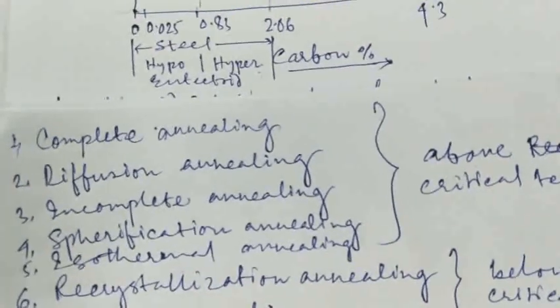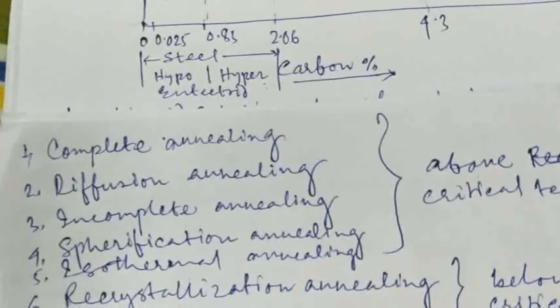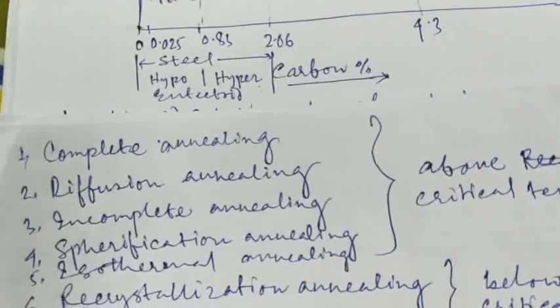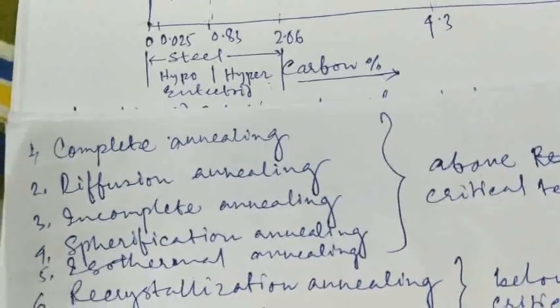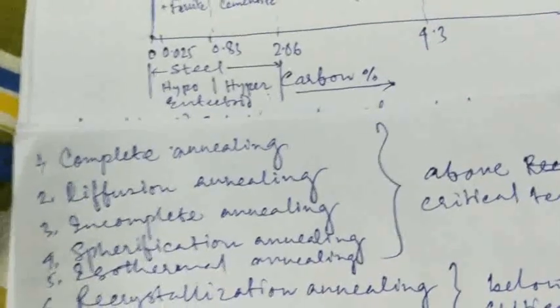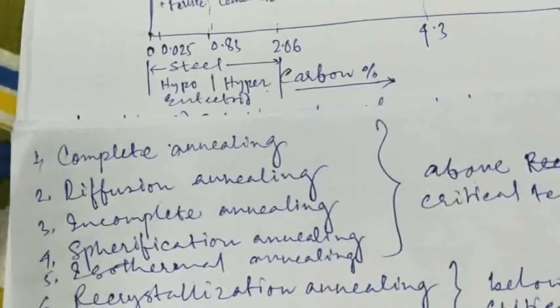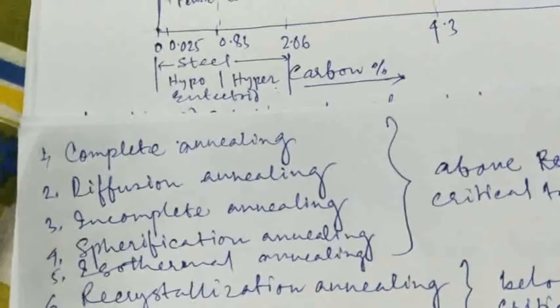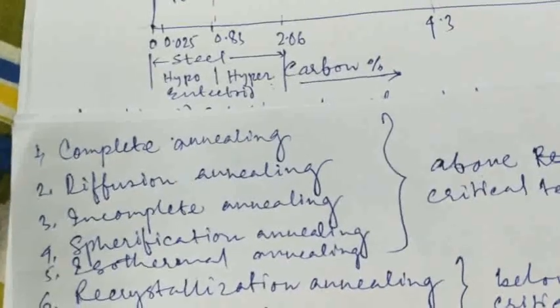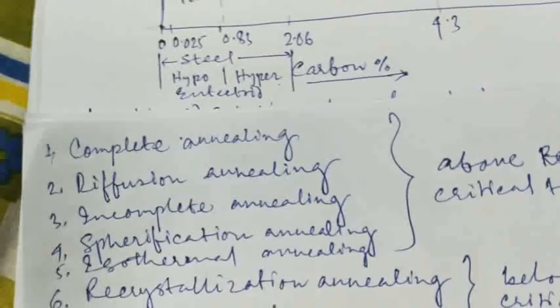What are the purposes of annealing? First, to reduce the hardness of steel, improve plasticity, and facilitate machining and cold deformation processing. Second, to make the chemical composition and organization of the steel uniform, refining the grain to improve the performance of steel or to prepare for quenching.